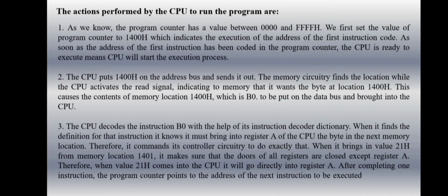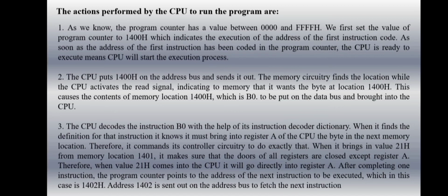After completing one instruction, the program counter points to the address of the next instruction to be executed, which in this case is 1402H. Address 1402 is sent out on the address bus to fetch the next instruction. Step 4: from memory location 1402H, it fetches code 04H.